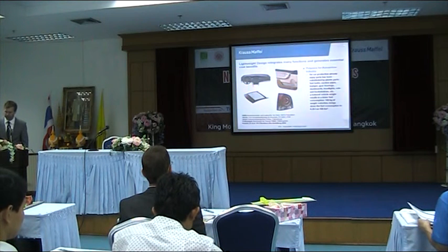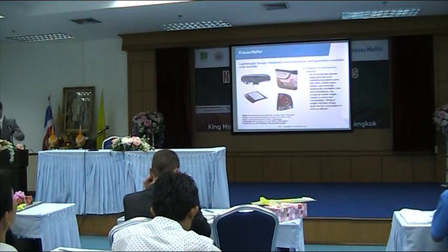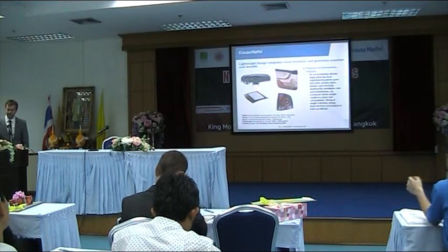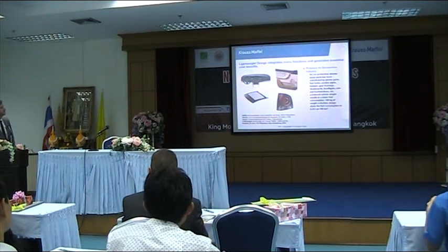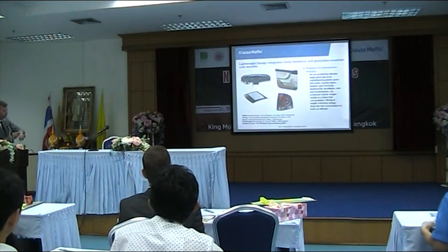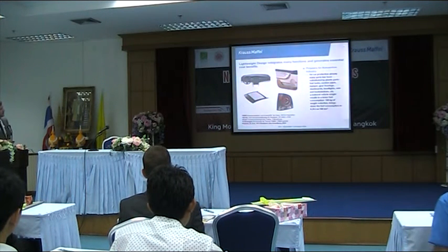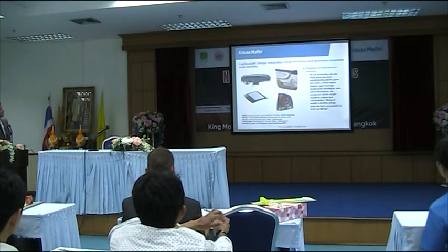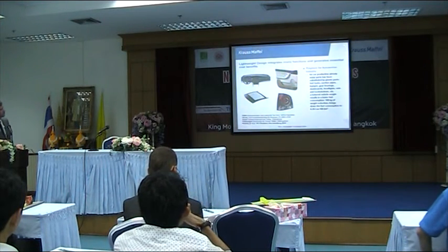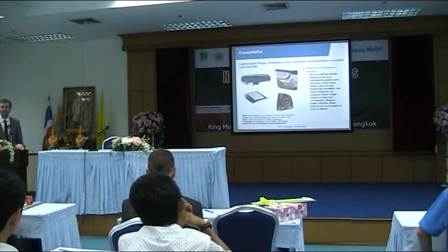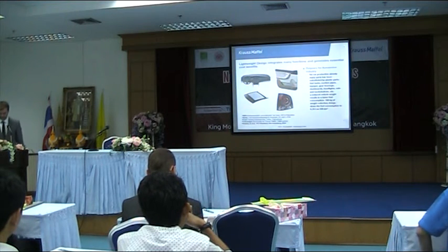For example, 100 kilograms of weight reduction brings down the fuel consumption by 0.35 liters per 100 kilometers. There are several parts: the glazing, the side, the interior of the door, the dashboard, and also lights. Almost everything is made in polymers now.